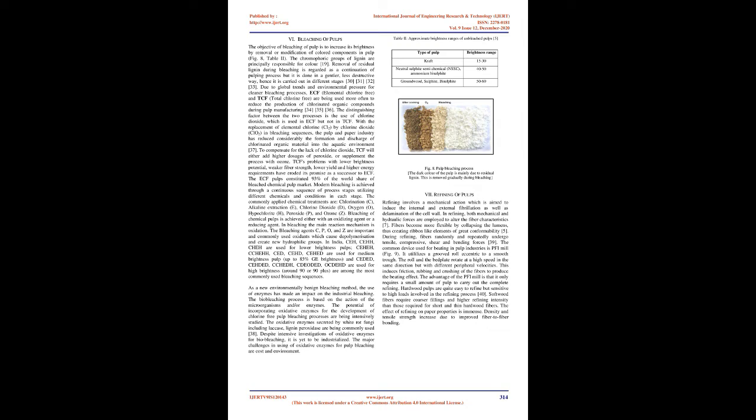B. Mechanical pulping. The principle of mechanical pulping is to separate fibers from each other by mechanical energy applied to the wood matrix, causing gradual breakage of bonds between the fibers and thereby releasing single fibers, fiber bundles and fiber fragments. 29. The objective is to maintain the main part of the lignin in the raw material in order to achieve high yield with acceptable strength properties and brightness. Mechanical pulps have a low resistance to aging, which results in a tendency to discolor.